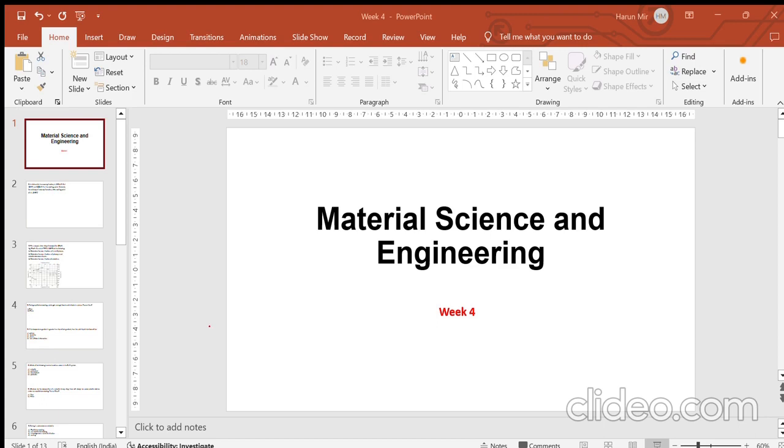So below your hypoeutectic, there is always a constituent of primary alpha, which solidifies along with your eutectic mixture. So you have primary alpha and eutectic mixture, while above the eutectic point you have primary beta and eutectic mixture solidifying from your liquid melt. So you have to calculate the primary alpha and eutectic microconstituents, and you also have to determine the mass fraction